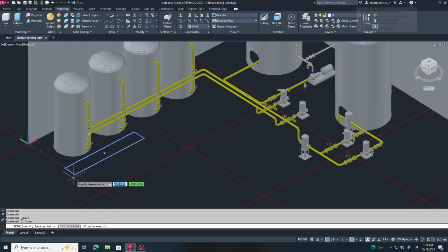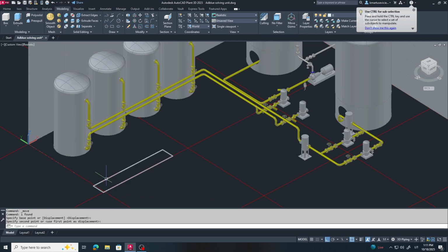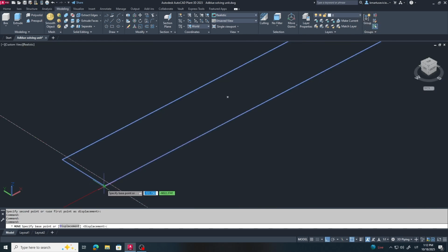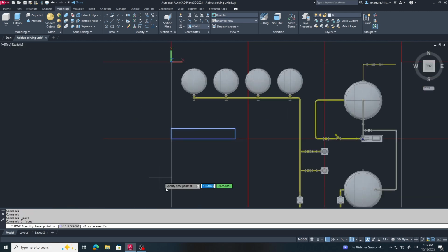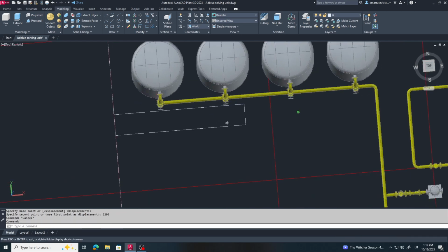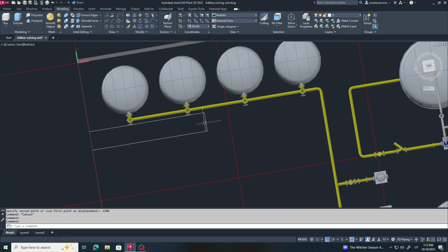In industrial layouts, maintenance walkways require certain minimum widths to ensure safe and comfortable movement for personnel. 600 millimeters is considered the absolute minimum clearance that still allows a person to pass and perform basic tasks. It's typically accepted only in tight technical areas where space is limited.